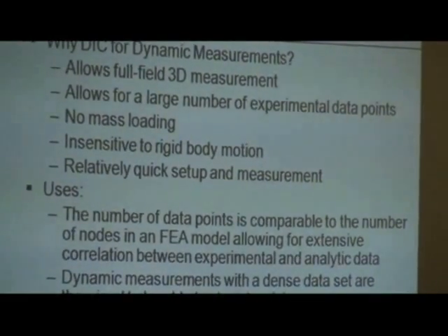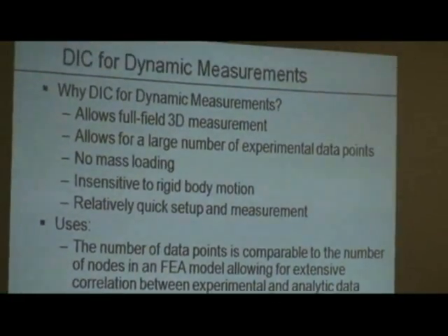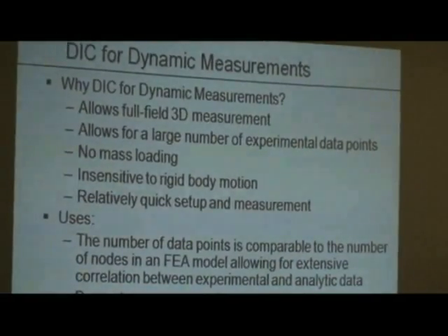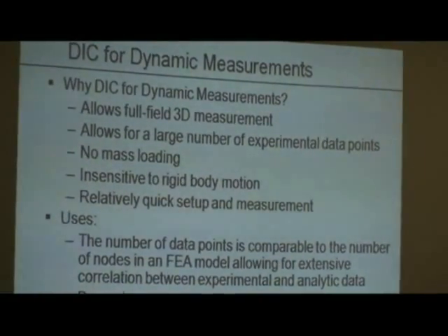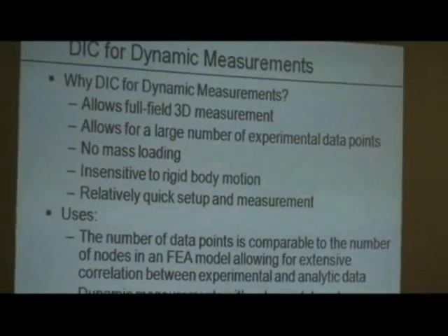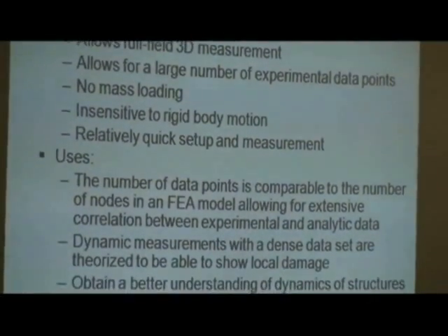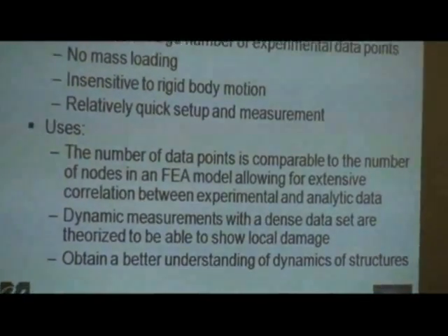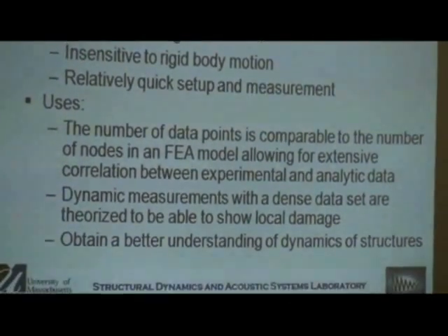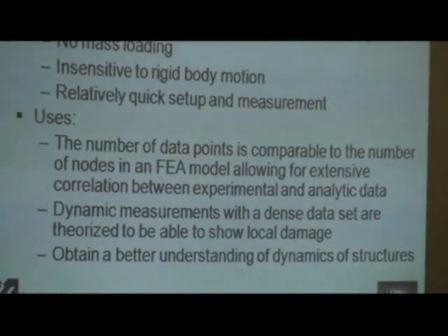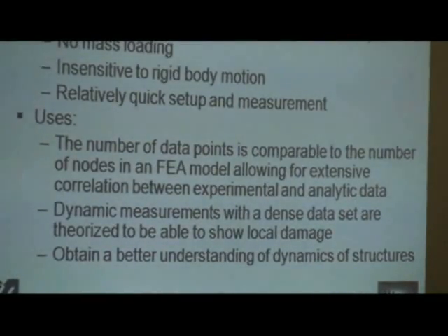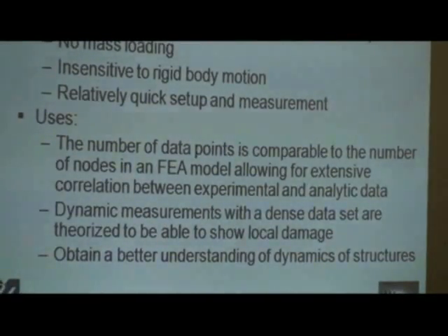So, in a nutshell, the next question is, how can we use this technique for dynamic measurement, and why are we exploring this? First we started using it for static applications, but then I realized this is a powerful technique that has application for vibration measurement. It's essentially non-contacting, except for the pattern that you apply, so there's no mass loading on the structure. And it provides spatially rich information about the structure, so we get a tremendous amount of information over a wide area.